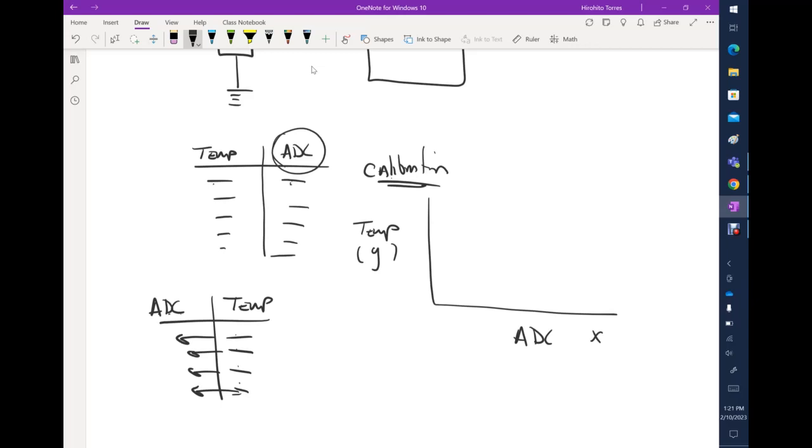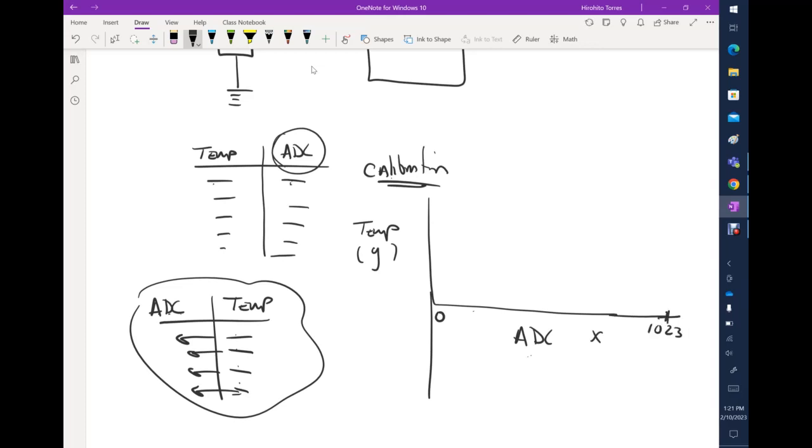I believe that doing it like this will be more aligned eventually to this, because what you're gonna get at the end, remember, the ADC is a value between 0 and 1023, which is the maximum. Let's say that 1023 is the maximum temperature you can get, 150, just to say a number, and the minimum is somewhere here when it's 0. So you have a curve like this, or like a straight line.